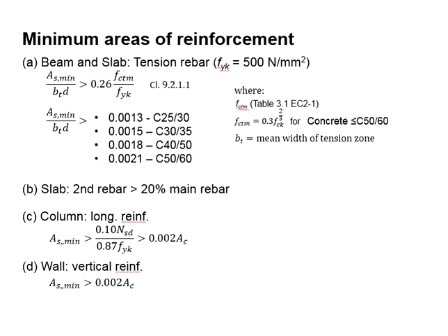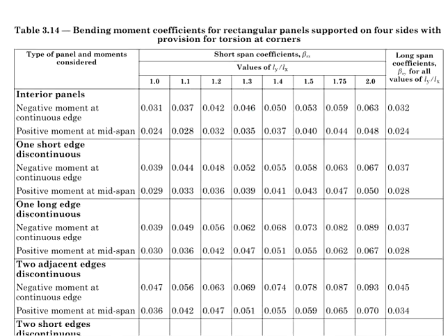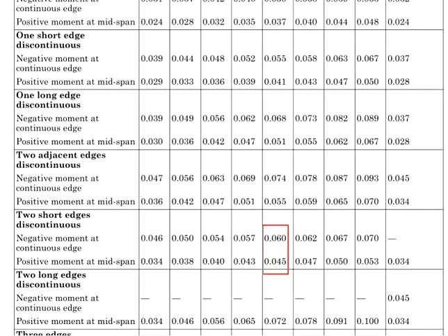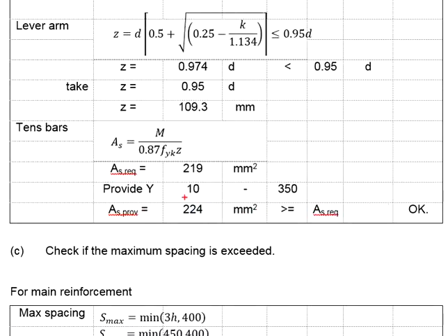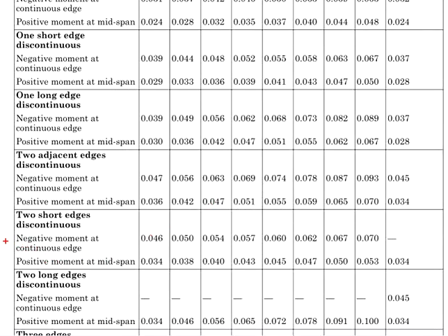And the minimum bar area for the slab, which we are referring to as the secondary reinforcement, should be at least greater than 20% of the main bar. By right, you will have to design the slab in both the longer span and the shorter span. When the ratio varies, the provided amount of reinforcement bar may vary. At the end of the day, you will have the design reinforcement in the shorter span and also the longer span, both at the support and also at the mid-span.